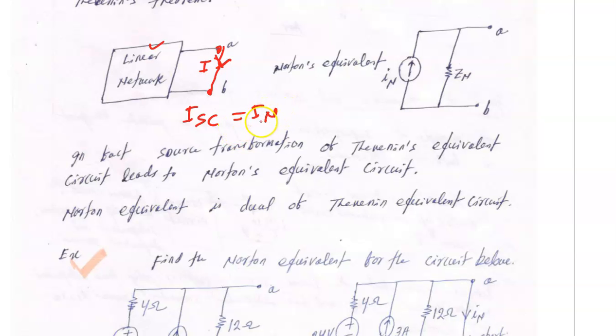Reduce all independent sources to 0, leaving their internal impedances, and operate all the dependent sources as usual. Then find the impedance looking from the terminals A and B. That is the Norton impedance. As usual, reduce the voltage source and current source to 0, keep the dependent sources operating, and find the impedance.